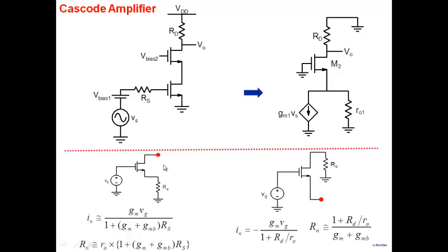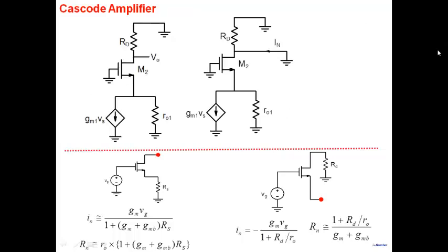All right. Once we have that, the next thing that we do is note that both these results that you see here rely on building a Norton's equivalent. So what we can do is, if I'm interested in the voltage at this node, I build a Norton's equivalent at this particular node. Norton's equivalent at this node means that the whole circuit, looking at it from that node, is a current source in parallel with RL. Okay, so let's do that.